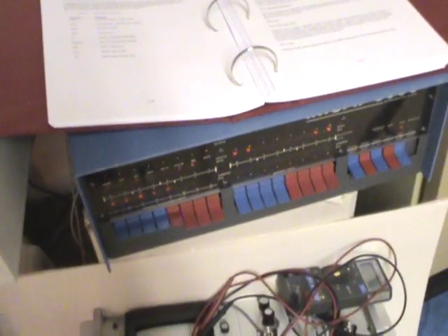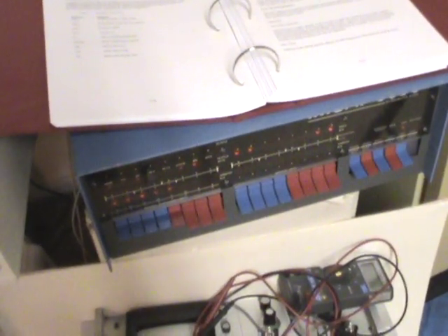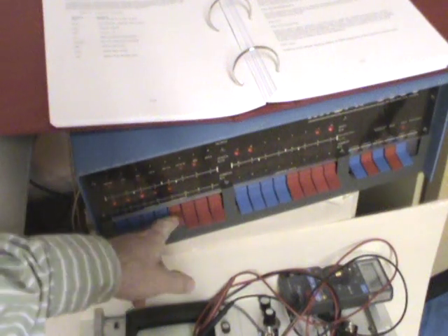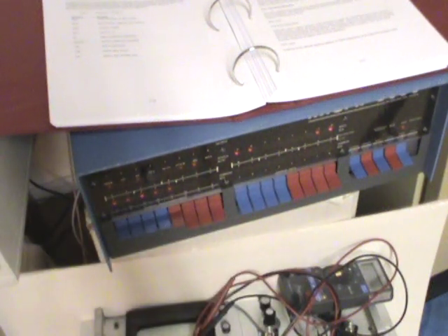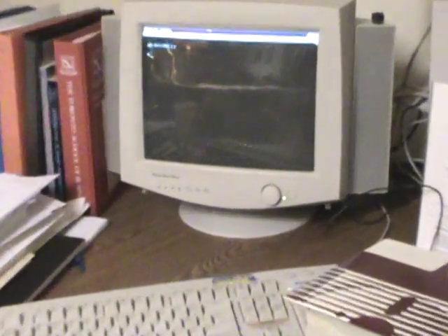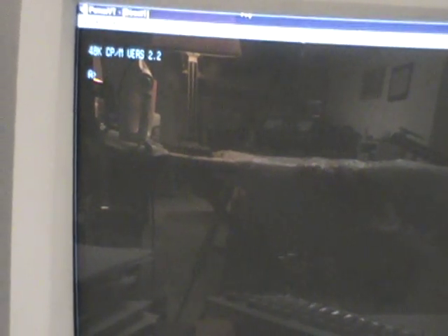I've set the IMSAI 8080 computer address at the start of the Disk Jockey EEPROM, F800, so that it would load the cold bootloader and start CP/M. So we just run the program. The disk is accessed and we're greeted with the 48K CP/M version 2.2 sign-on message and the drive A ready prompt.